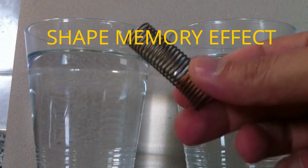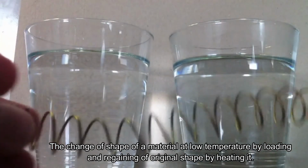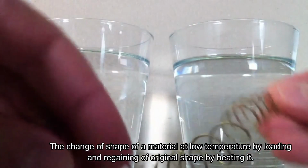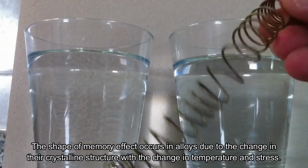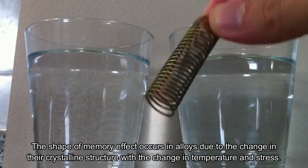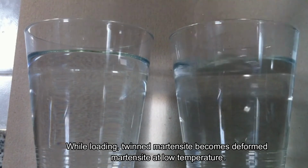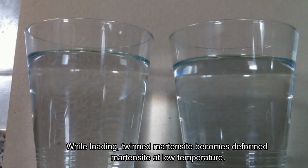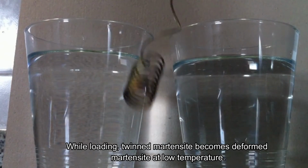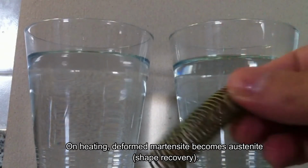Shape memory effect. The change of shape of a material at low temperature by loading and regaining of original shape by heating it. The shape memory effect occurs in alloys due to the change in their crystalline structure with the change in temperature and stress. While loading, twinned martensite becomes deformed martensite at low temperature. On heating, deformed martensite becomes austenite, the shape recovery.